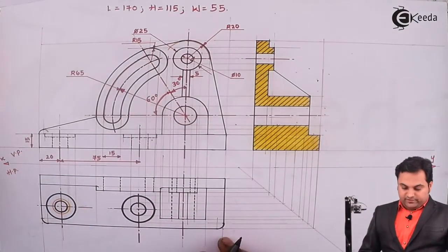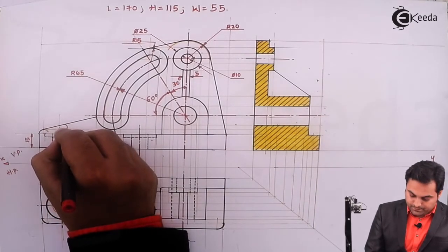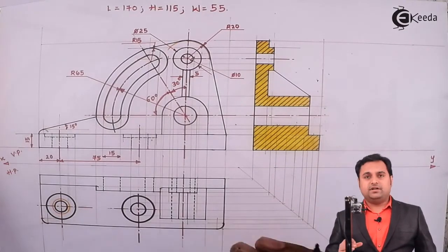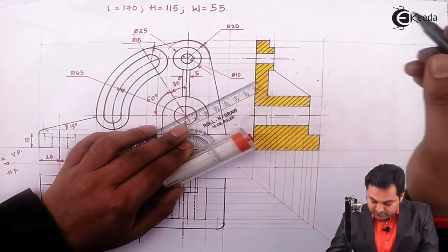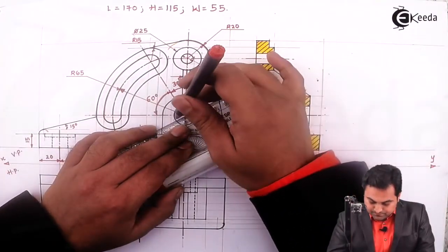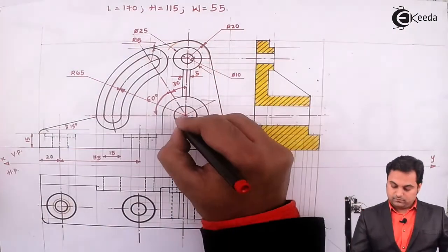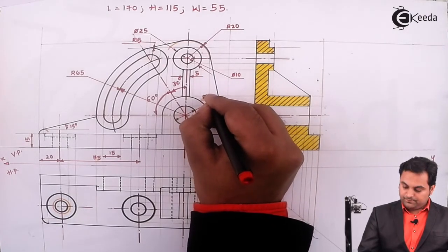This height is 15 mm, and the angle made here is 15 degree. Maximum dimensions are there on the front view itself, so I have to give the maximum details here. This diameter is 20 mm.